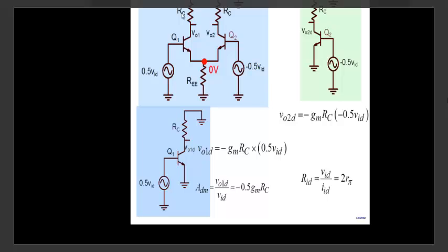But what happens is, note that if RC and RC here are different, what are the consequences of it? The voltage here and the voltage here are going to be different. The bias points are also going to be different, right? The same current, but the bias point here and the bias point here are also going to be different. But note, because of differences in the collector voltage here, whatever is the voltage here, whatever is the voltage here, it doesn't have too much impact on the current, because how does the collector voltage affect the current?